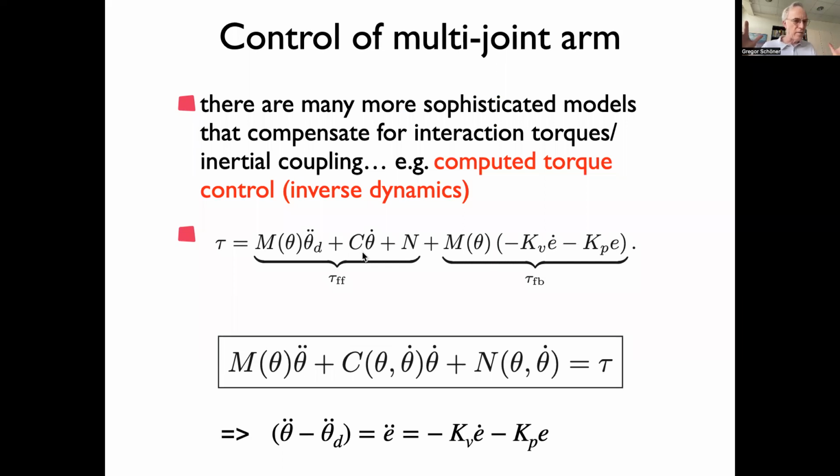If you imagine you have a 6-degree of freedom arm, it's this huge matrix that has a lot of nonlinear terms, sine, cosine, and so on. And you have to compute all of that in real time. At every moment in time, that matrix will be different. You have to compute it afresh at every moment in time, let's say at a rate of 500 hertz. So you have 2 milliseconds to make the computation, and actually less than that because you also have to implement it. So it's quite computationally demanding.